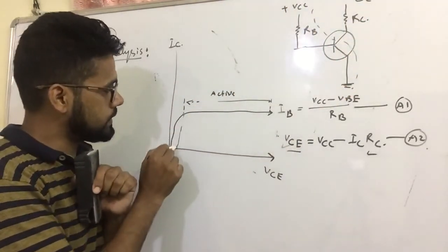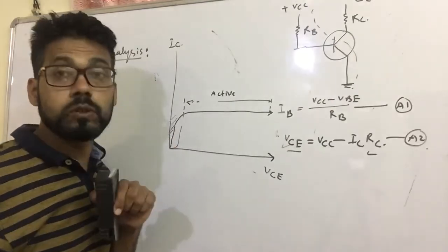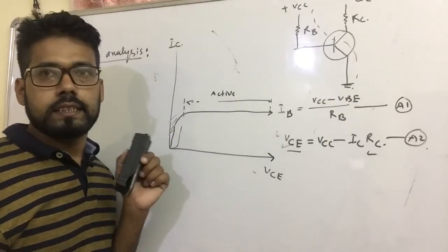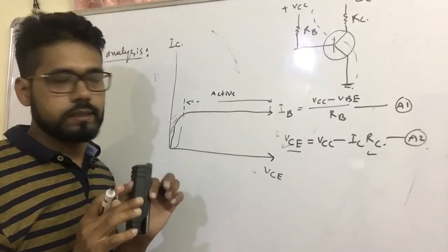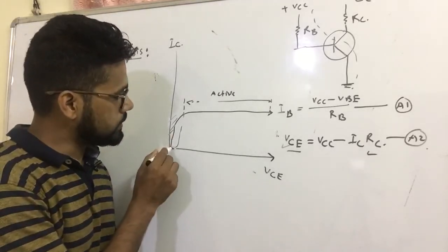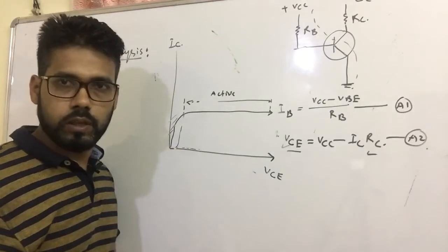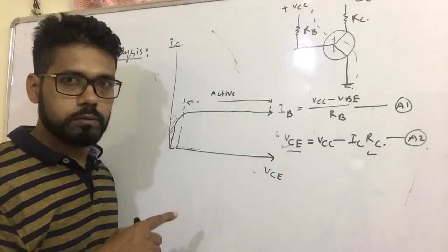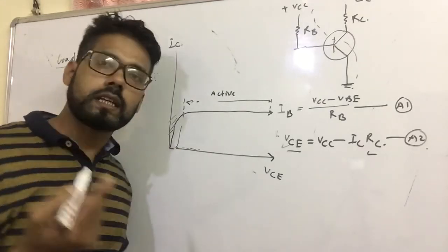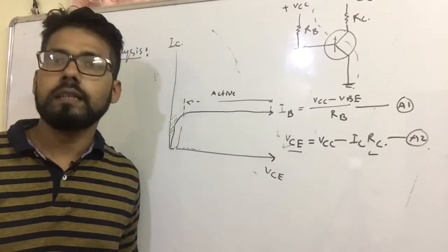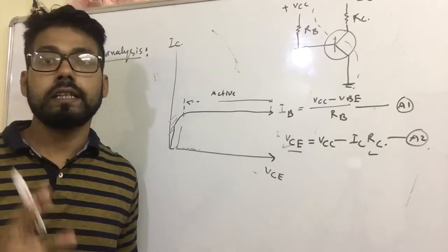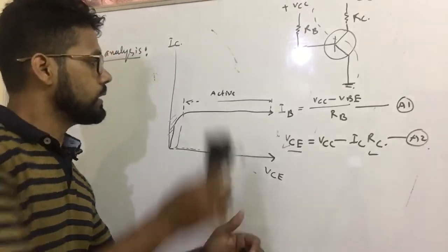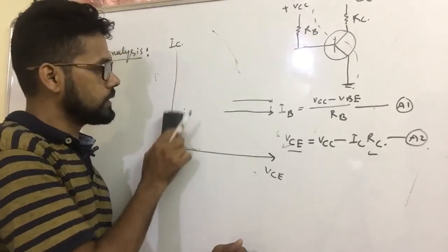In this region, both the input circuit and the output circuit will be forward biased. And the cutoff region is very close to the horizontal line. In this cutoff region, both circuits will be reverse biased. For amplification purposes, we want to apply the transistor in the active region. So forget about that. Now I am removing this part again.